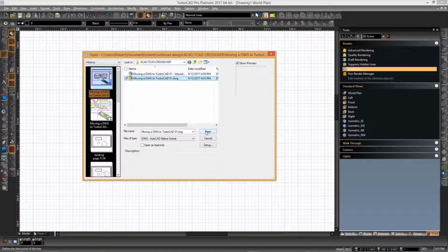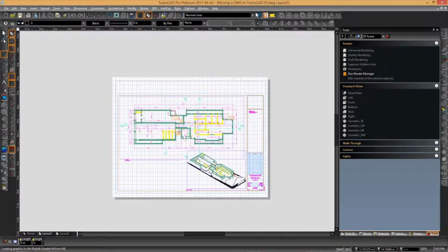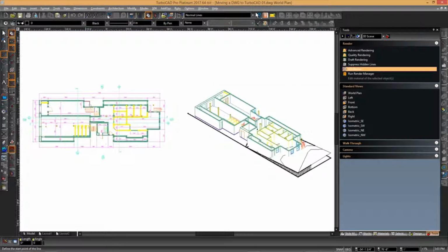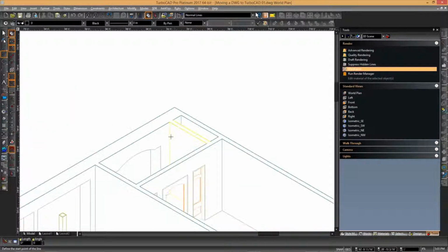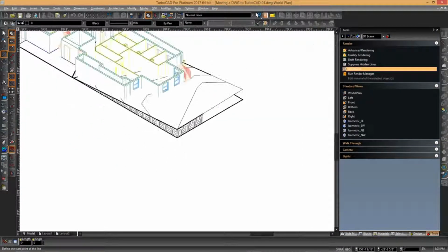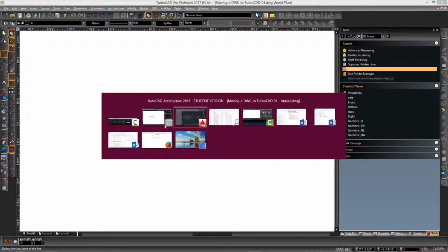Once the drawing is open in TurboCAD, you can switch to the model space. On the standard toolbar, we see several buttons dedicated to the zoom functionality. Specifically, the Zoom to Extents button with the keyboard shortcut Control Backspace will provide similar functionality to that illustrated in AutoCAD. It is easy to zoom in and out to specific areas of the drawing by firstly moving the cursor to a point of interest and then rolling the wheel mouse back and forth.